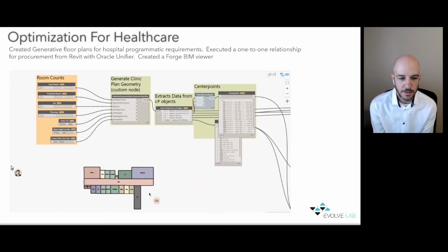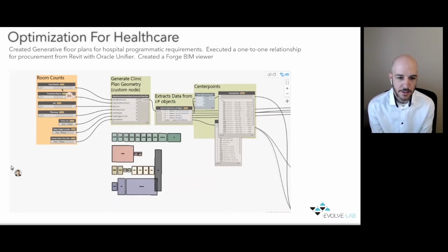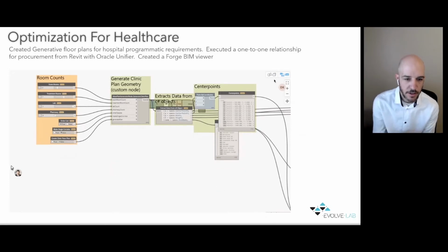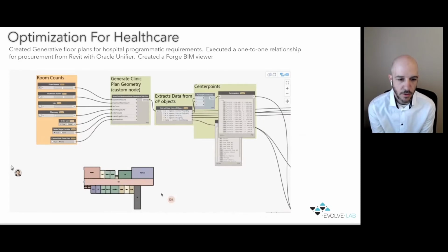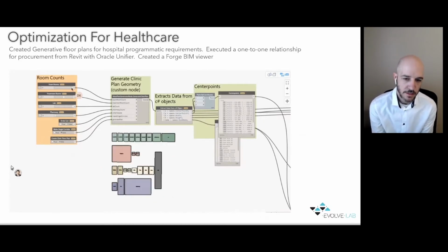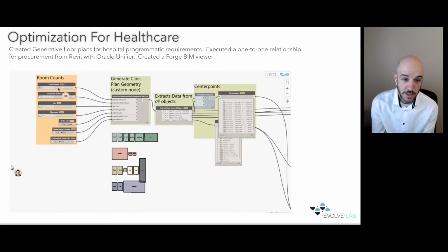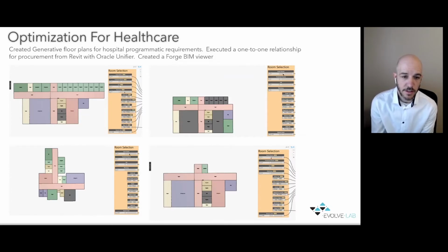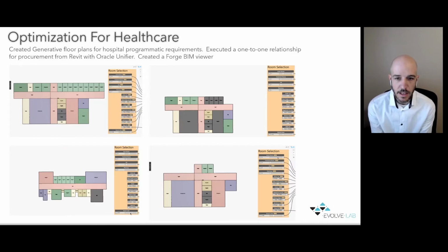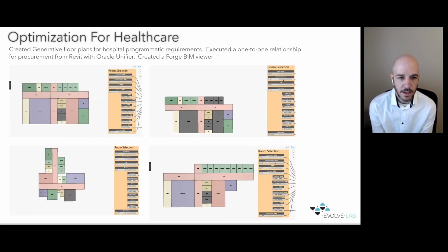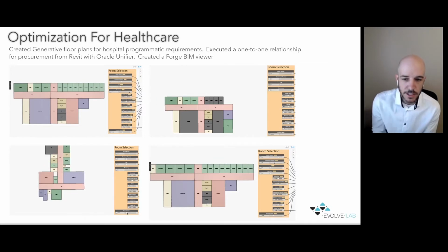And what we wanted to do is create a generative design tool that, as you have those various blocks, algorithmically the computer could go through and start to lay out those spaces, but then apply corridor width associated to those spaces. And then taking it another level further, we started looking at branching structures, different hallway layouts, seeing how the different spaces would actually interact based on different algorithmic solutions and different branching diagrams.